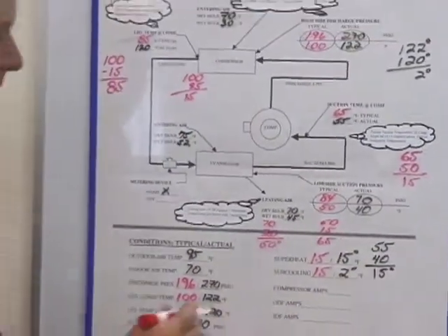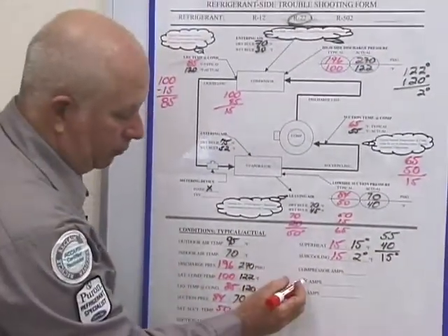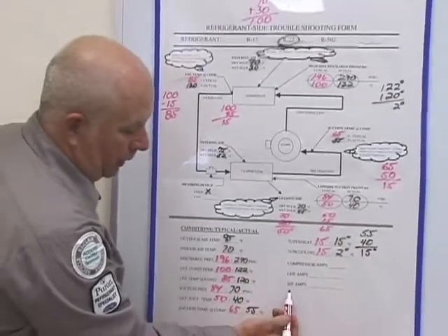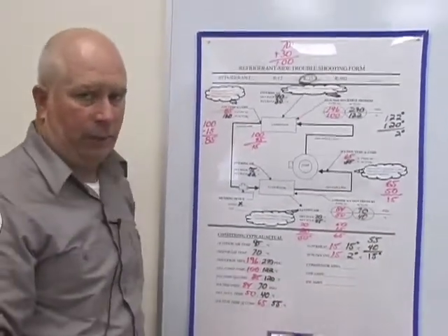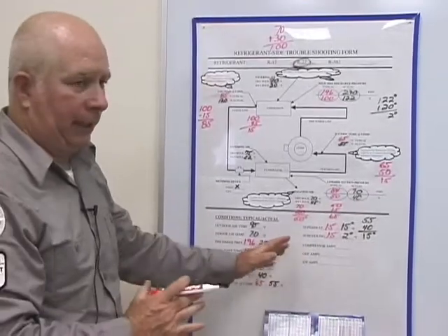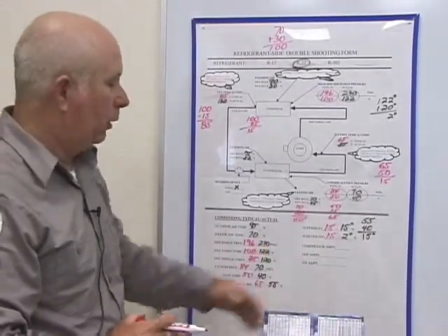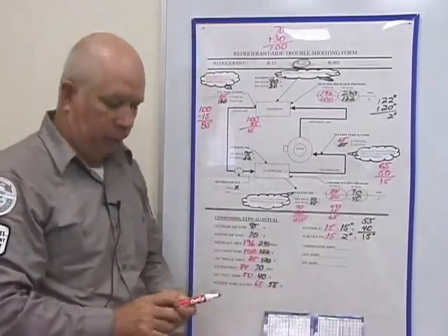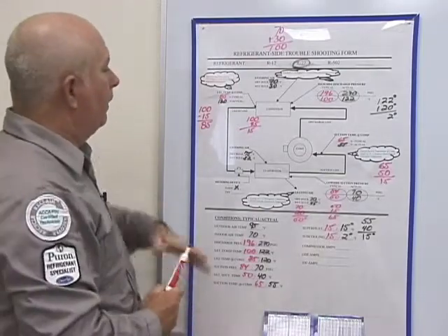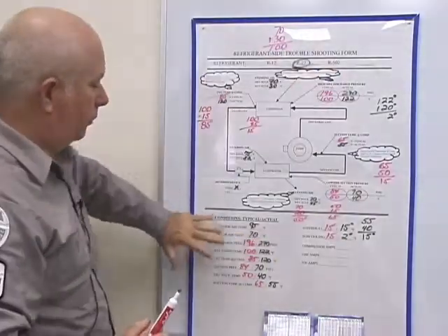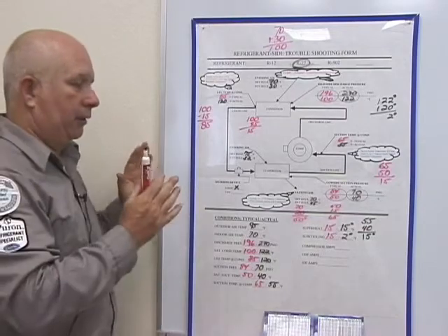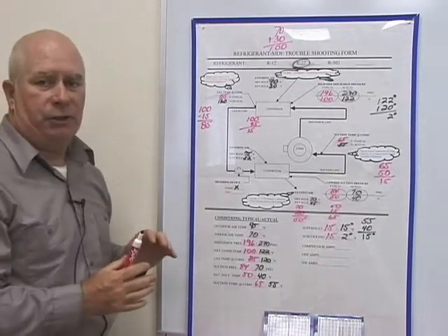Now, minus whatever you get here in the compressor amps, outdoor fan motor amps, and the indoor fan motor amps. We won't deal with that quite yet. In our last phase we will, and I'll put some erroneous numbers up there so you can figure out how to use that. But now we have all our numbers filtered out and placed in the proper position.